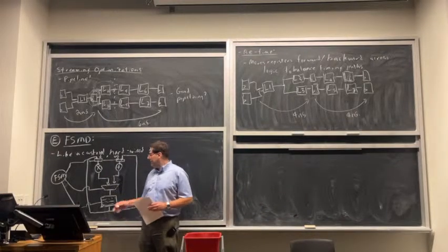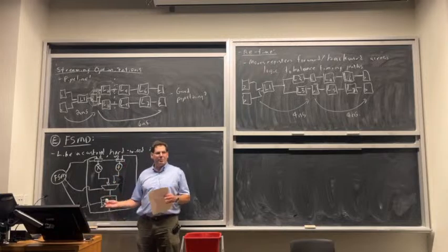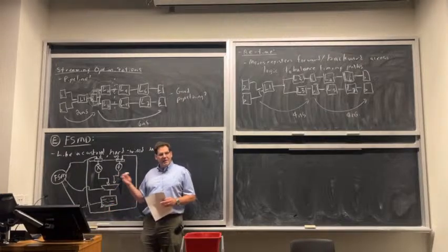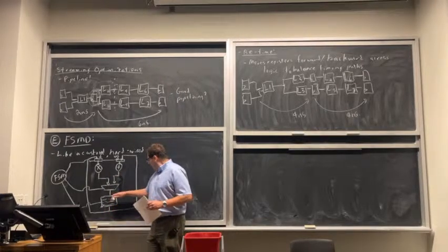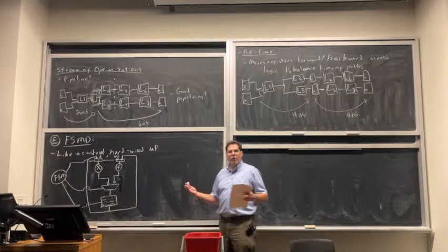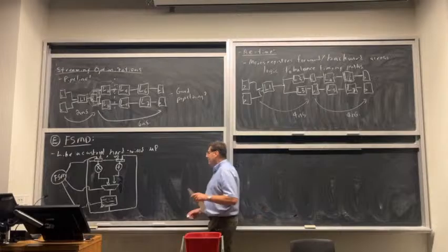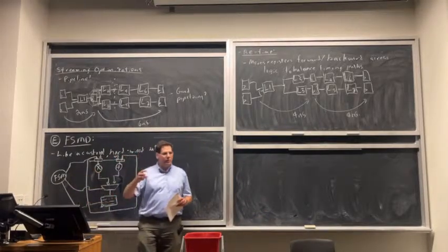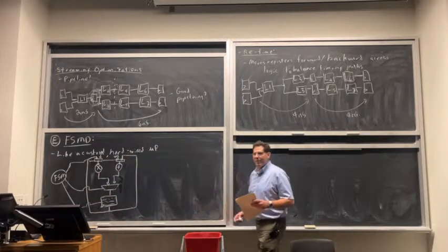Now in a processor, you generally make this data path pretty general. It can do anything. Here you make the data path only have the operations that you need, so it's kind of stripped down. You probably make the register file only as big as you need it. You make however many registers you need for your temporaries, and that's all the ones that you make. You have multiplexers to select them, and a finite state machine that walks through and just controls the state of every mux.